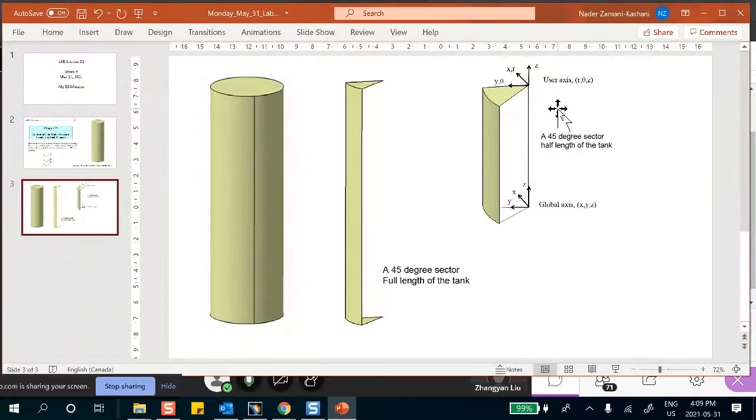So I can use the good old user-defined restraint and say translation in 1 and 2 and 3, etc. You know the rule. But if this is 45 degrees or 30, anything but 90 pretty much, then one of them can be thought of as being in the XZ plane or YZ plane. The other one is going to be off that plane.